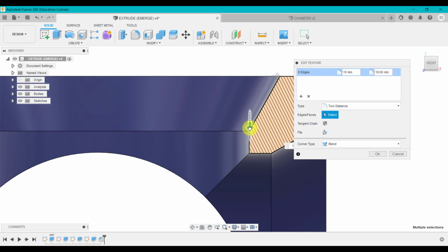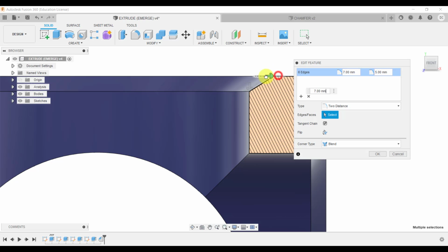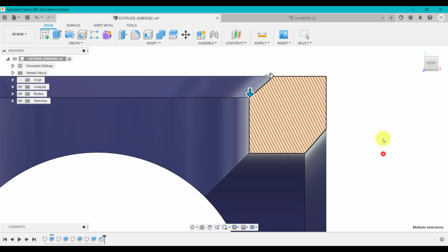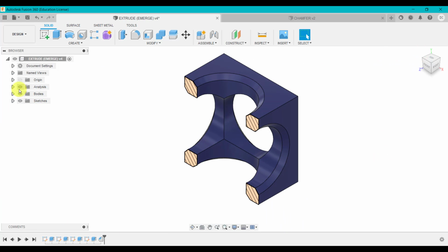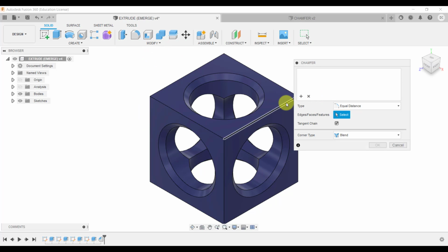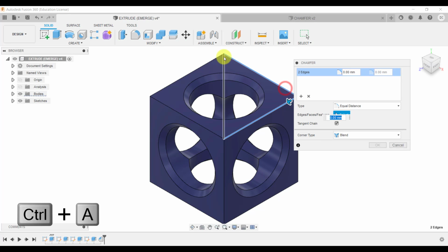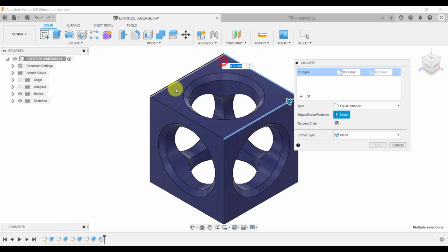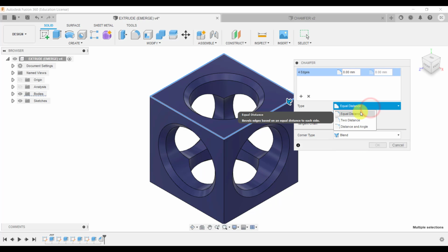And you can drag it, so visually if you wanted to change it, you've got options with dragging that in and out as well. And of course, these dimensions will change. Let me just take that analysis off. So we've done that chamfer in the middle. What we're going to do now is go to chamfer again, and I'm going to choose all these outer points. Oh, actually, I'll choose the top edges, I reckon. There you go.